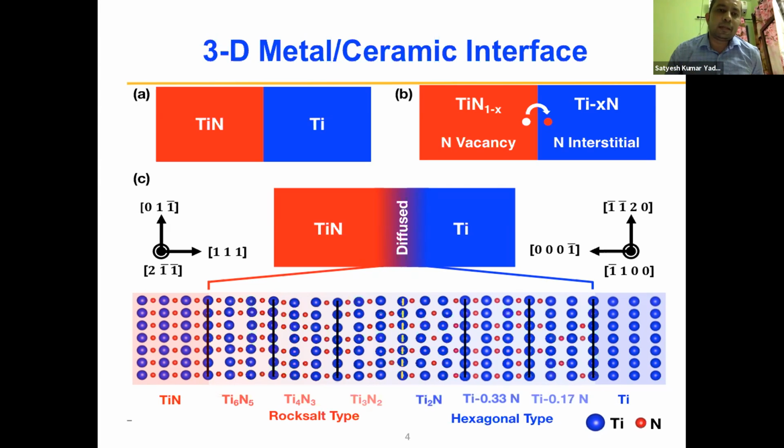Well, there is only a limited thing that can happen between titanium nitride and titanium, which is mixing of nitrogen across the interface. So one would safely assume, and talking to a lot of people who are actually doing experiments on titanium nitride, it being a very popular heterostructure, simply because titanium is a biological implant. It is used in aircraft and other places, and titanium nitride is a coating to prevent erosion of titanium. Wherever there is wear and tear, they try to coat it with titanium nitride. So this is a very popular one.